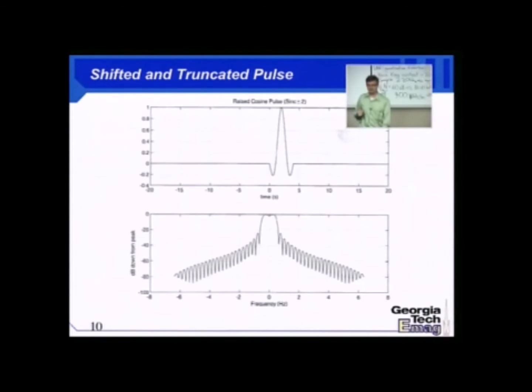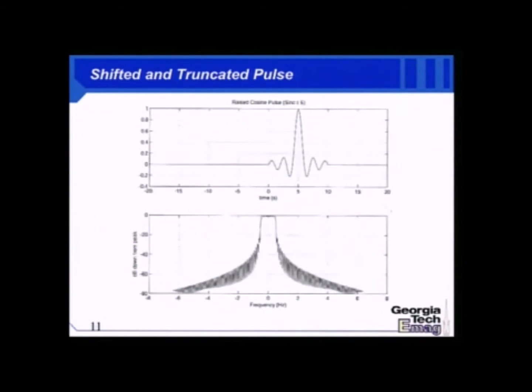The other option that you have is to change the pulse shape. Maybe I need to expand the cycles of the sync. What would that do? Well, now here's a causal sync with about 8 cycles in there thrown in. Let's say 1, 2, 3, 4, 5, 6, 7, 8, 9, 10, 11. So about actually 10, a support of 10 symbol periods. And look how nicely that rolls off in the dB scale. You see, adding a few extra lobes goes a long way for collapsing your signal strength into a finite band.